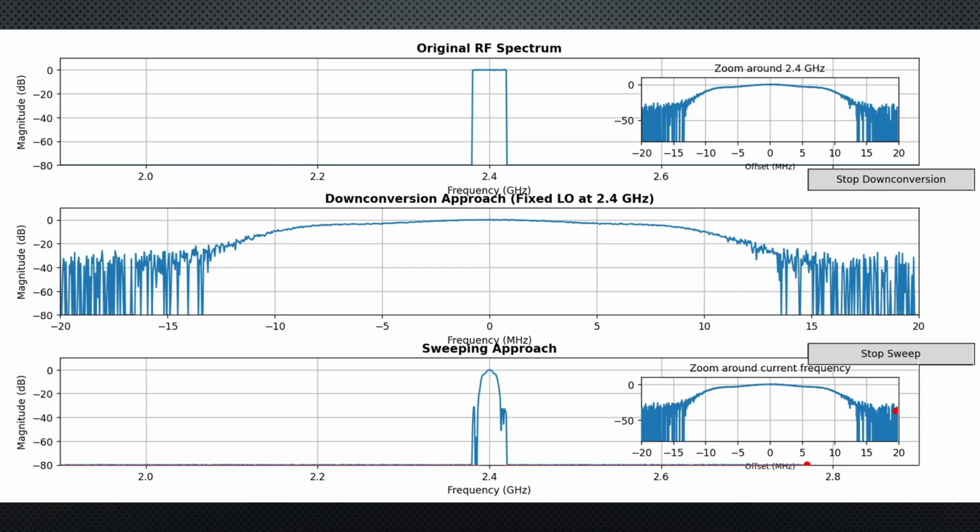In the last video we talked about how to create a spectrum analyzer using ADALM-PLUTO. The way we did it was using a mixer at the receiver to downmix the received signal, then convert the baseband signal in time domain, which is recorded by our ADC, to frequency domain using a Fourier transform.